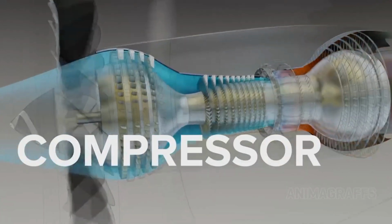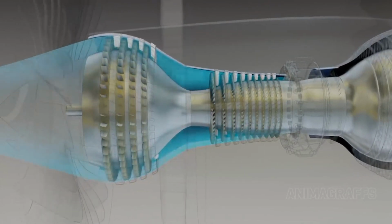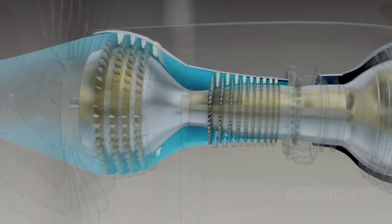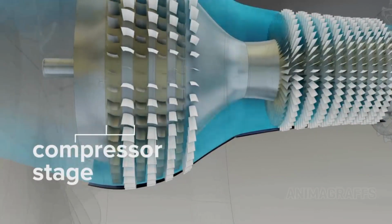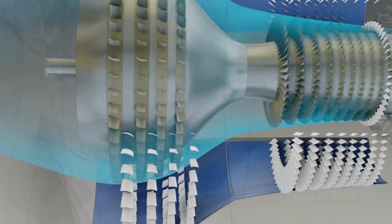The compressor. Compressed air makes for a much more powerful combustion reaction relative to engine size. Compression happens in stages that force incoming air into an increasingly narrow chamber. A single compressor stage is comprised of a spinning rotor paired with a ring of stationary stator vanes which are attached to the core casing.